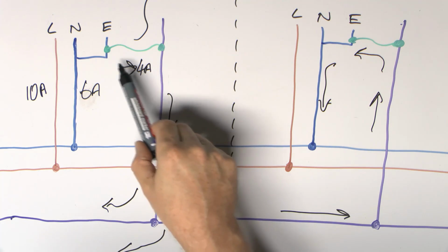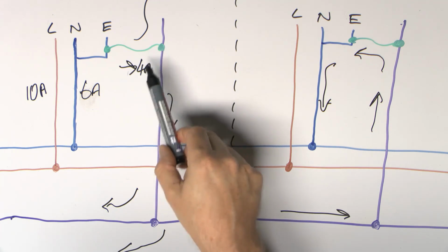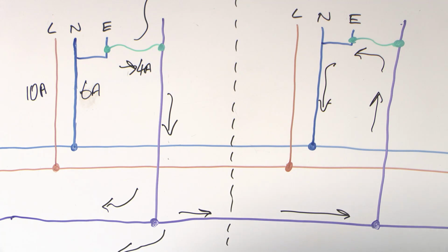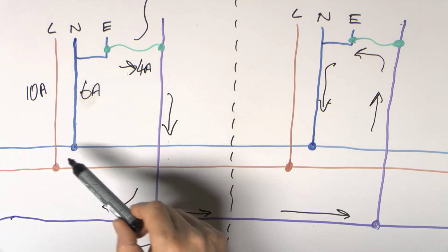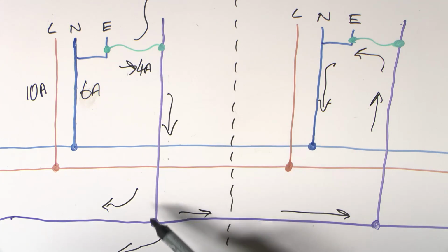So if you go to an installation, put a clamp meter around the bonding conductor and find there's current there, it does not mean there's some kind of massive failure occurred and you have to call people and all the rest of it. It could in fact be normal operation of a TNCS supply. Now if you were to turn off this supply and isolate it, there won't be any current here, so you wouldn't expect any current here either.